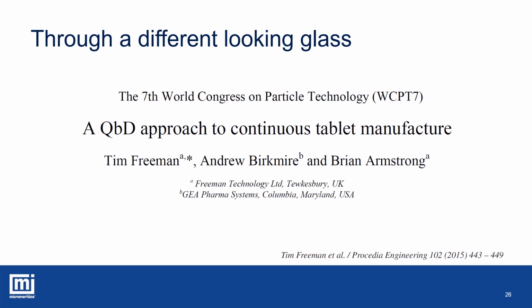The paper illustrates a path to understand tablet production and shows that through understanding and controlling the materials and the processing steps, you can generate a finished tablet with a desired hardness. As hardness is nearly always a critical quality attribute of a tablet, this is a significant bit of work. I also like it because it essentially repeats all the things I have previously tried to illustrate in one neat package. I'll take you through the highlights, but the reference is there, and I highly recommend reading the whole thing if you have the time.